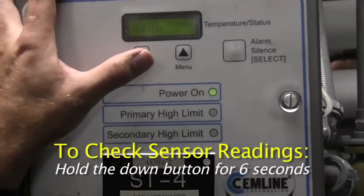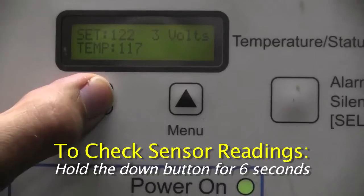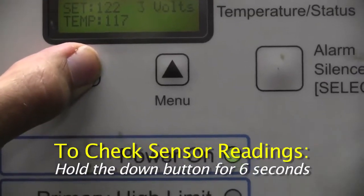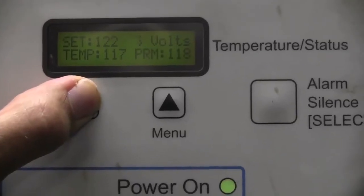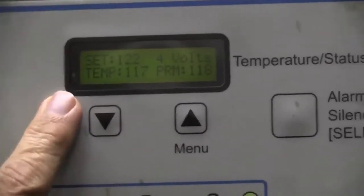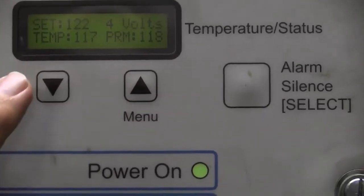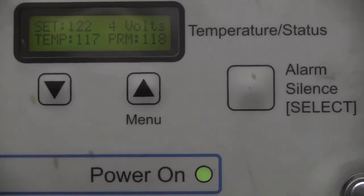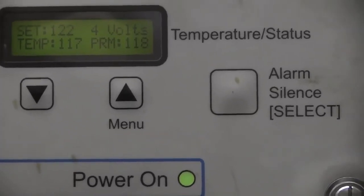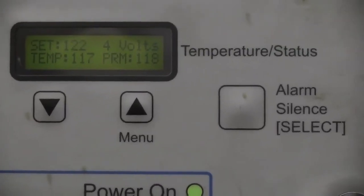So if you wanted to check to see what your sensor readings are, you're going to hold the down button for about 6 seconds. That's going to show you the reading for your primary and your secondary sensors, and we do want those within 5 degrees apart. If it's more than that, you have an issue with either your sensors or your circ pump, and we would go through other diagnostics to figure out which is which.